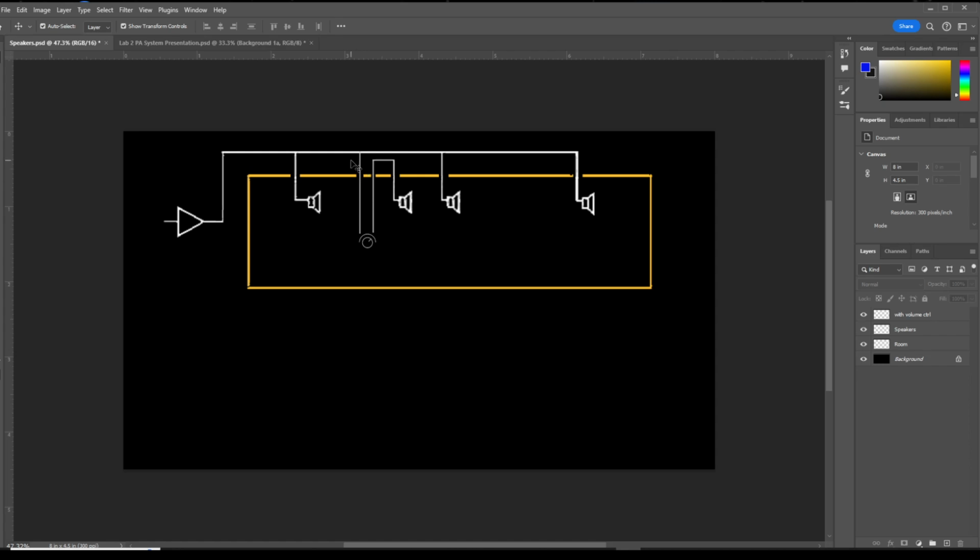So we get the output. We tap into the main bus, main audio line, connecting it in parallel, basically red to red, black to black. Boom! It goes right into the input of the volume control, usually in the conduit inside the wall. Now, through the same conduit, we run the wire back into the ceiling space from the output of the volume control, and then we run that into the speaker station. So the volume control controls just that speaker station.